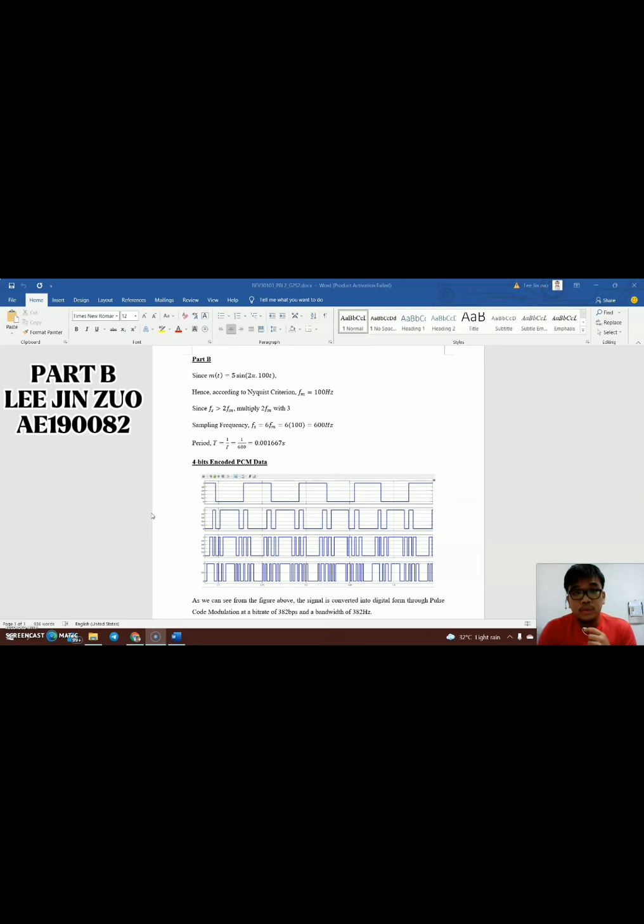BEV30103. Now I'm going to present you the PBL2 for the Part B section. So since m(t) = 5 sin(2π100t), according to the Nyquist criterion, Fm = 100 Hz, and also Fs is greater than 2Fm. Multiply 2Fm by 3. So sampling frequency Fs = 6Fm, 6 times 100, which equals 600 Hz.